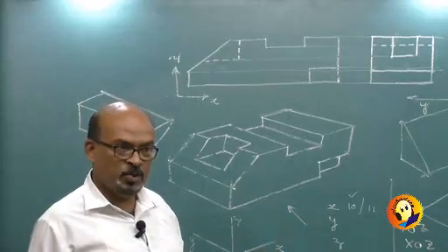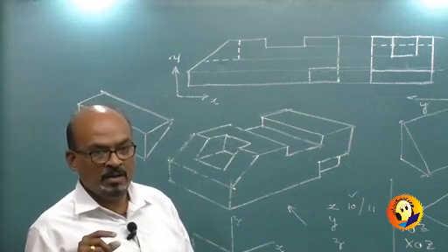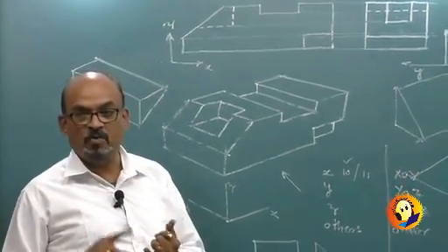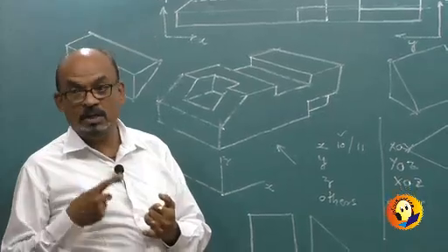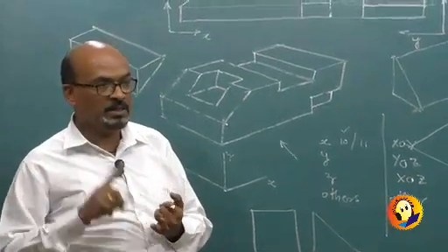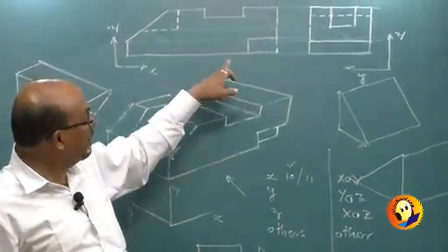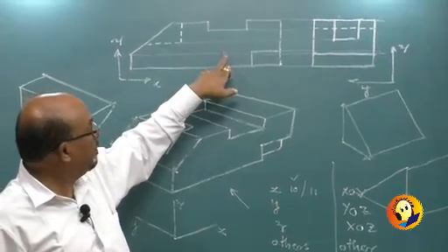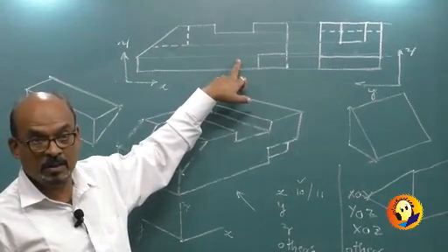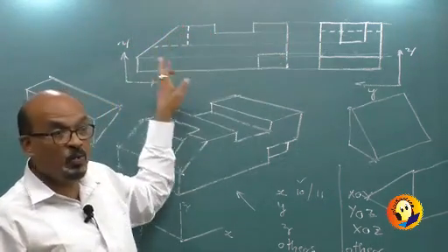And it is time consuming. We will take sufficient time so that we draw it properly, and we will pay attention first of all to the line work, because that is very important. It is not just that you have drawn it, because line thickness and darkness are to be maintained. All the lines are of different nature. Even if you see here, this line appears fainter than this, because it is just a construction line. The final projection, whatever I have, has to be equally dark and thick.